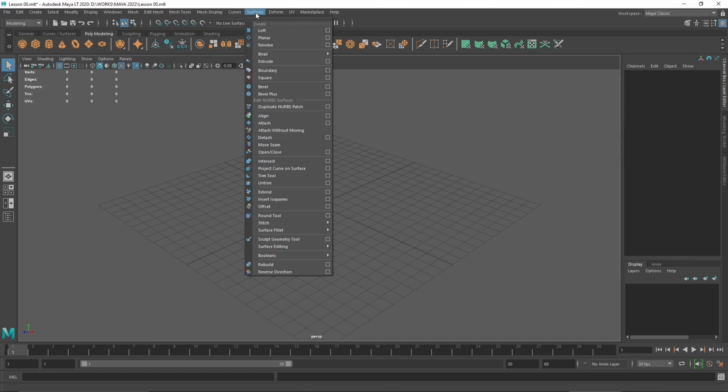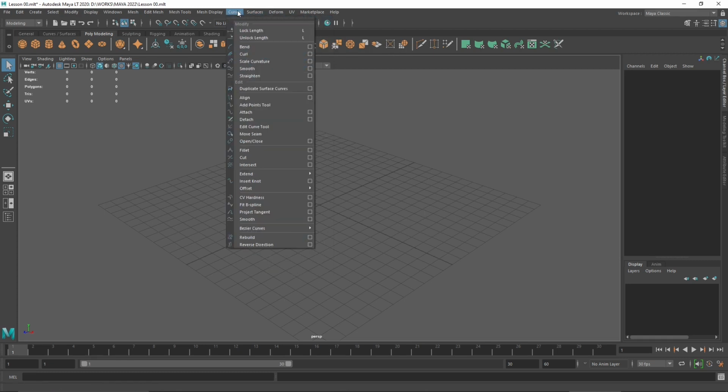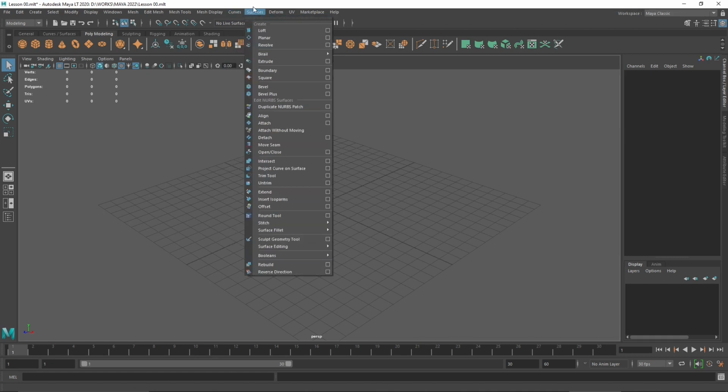And then we have also here other tools for surfaces, which are gonna be NURBS surfaces. So I don't think that you will find here the term NURBS, but this is what they are. When you use curves, you can then convert curves into surfaces and then convert surfaces into solids, into 3D objects, which are gonna be polysurface and closed polysurface.